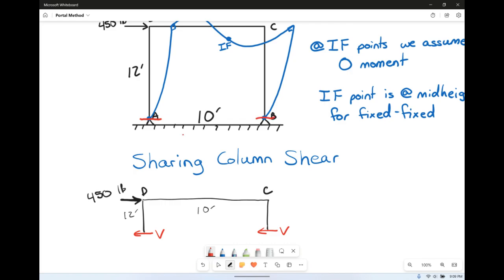Now for each bay, they're each going to have one shear. If you had a second bay that was right next to it, then you would have an additional shear, which makes the interior bays a total of 2 shears if there are multiple bays. The ends still get 1, but the middles get 2 because, again, with superposition, they would get twice as much. So we're just going to ignore that for now, but the more you know.